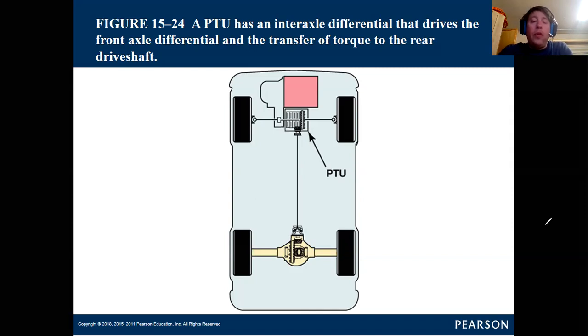When a driver of a vehicle is experiencing wheel slip and trying to accelerate at the same time, it would go ahead and lock in the four-wheel drive unit very violently and crudely. As we've advanced into what I'm talking about now with all-wheel drive, we're trying to accomplish the same goal, but we're doing it with viscous clutches. And so clutch packs have more give. They're not going to be a violent gear-on-gear spline linkage bang, into motion.